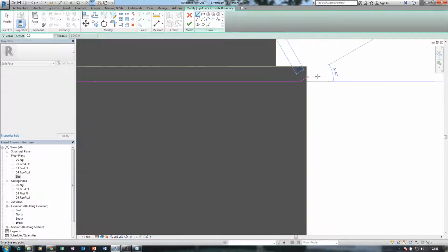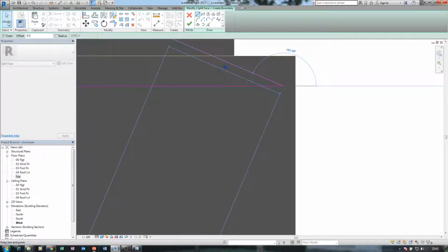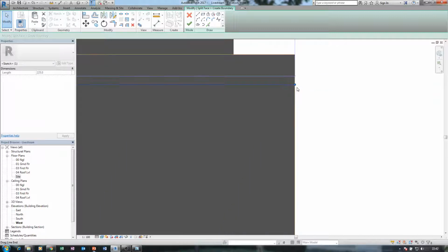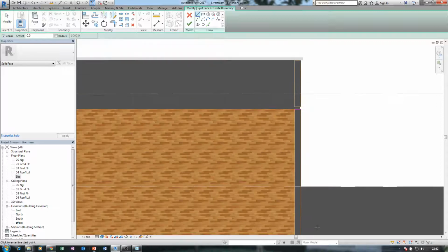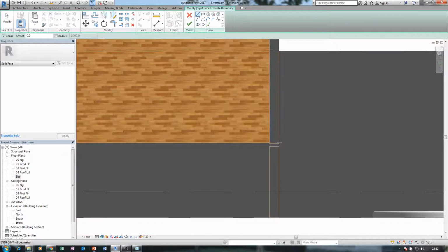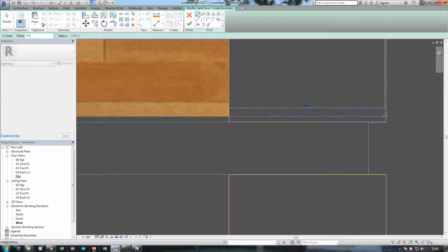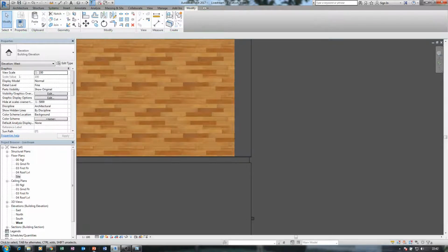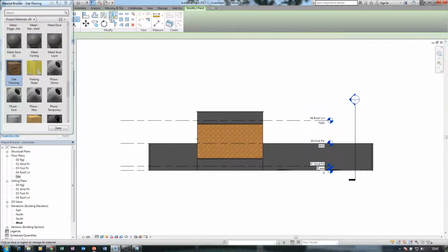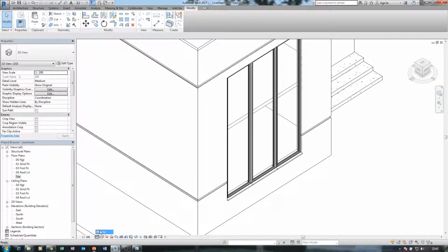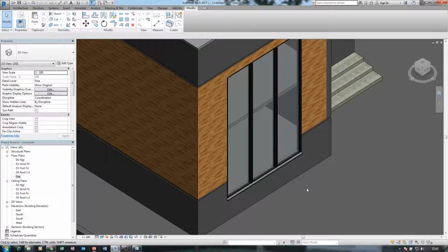And you can see it must not go beyond the boundary. That's the only rule for splitting faces in Revit. It must be enclosed. You can see, finish. So if it's not enclosed, Revit will start telling you something is happening over there, and it might be frustrating sometimes, but yet that's the advantage of Revit. It will allow you to do a great job, so you cannot fake it.